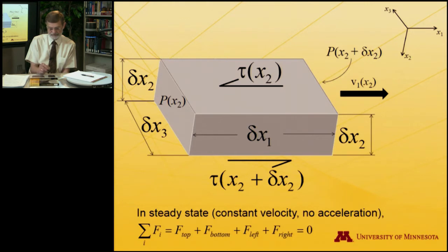First, we said there's a pressure gradient, right? So there's a pressure on the left-hand side and a lower pressure on the right-hand side. But there's also a shear stress on this cube because this plate on top, if we pull that plate across the top of the fluid, it's going to exert a shear stress on that upper surface. And so I've shown the shear stress here on the top, and here's the shear stress on the bottom surface.